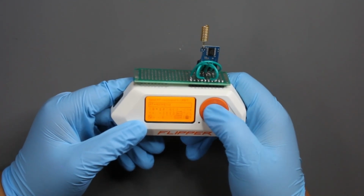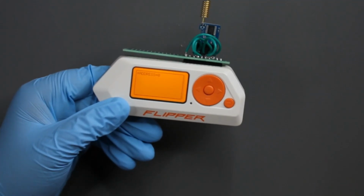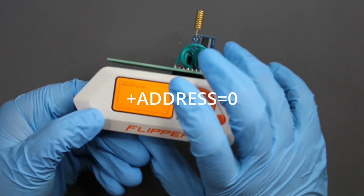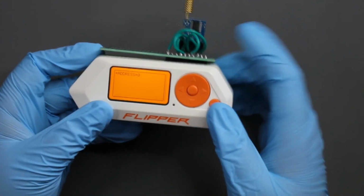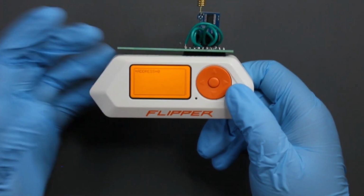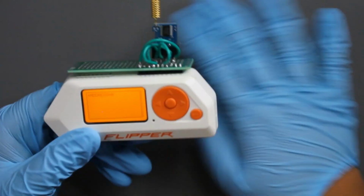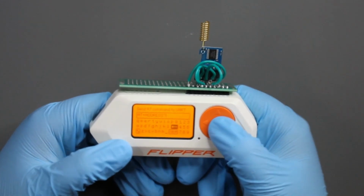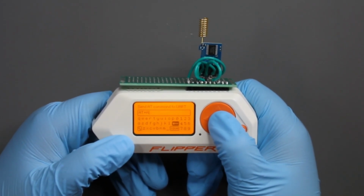So just do a question mark and save. And you can't see it right here, I don't know if you can. It says plus address equals 0. You're going to have to pick, or it'll show your address on your LoRa module. I don't know if it's the same for all of them, but this is the address for my current LoRa module. You can change it if you want to make it more encrypted, but that's basically it.